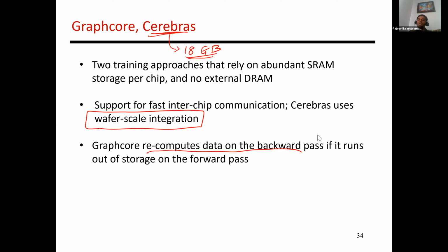So does the analog computing system have a scaling problem? Yes, it does, right? That's why we worked so hard to distribute the computation in time and space so that the value does not explode and go past the range of the ADC. We said that I'm implementing an 8-bit ADC. Because of that, the contribution from each cell can only be so much, and I can have only so many rows in each crossbar, right? So I was very careful to not exceed this analog range. It does have that scaling problem, and that's why we have to be very careful in that design.